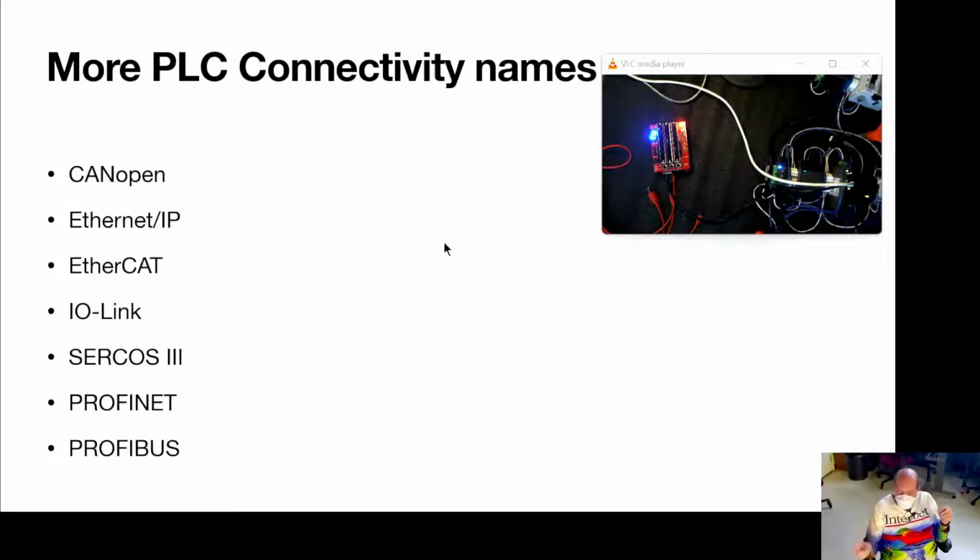What's really cool when you're doing automation in the Allen Bradley world with Ethernet IP is you will get an XML file from whatever vendor you're buying a thing from that you're integrating with that defines the message structure, that has all the variable names and types defined. So you'll say, I'm connecting to a new thing. The new thing is the servo drive. You load the XML file for the servo drive, and suddenly all of the variables communicating in both directions are already defined. Unfortunately, if you're not in the Allen Bradley world, that XML file might not be the one that works for the PLC you're working with. So that does save you a lot of trouble over reading data sheets in the Modbus example.